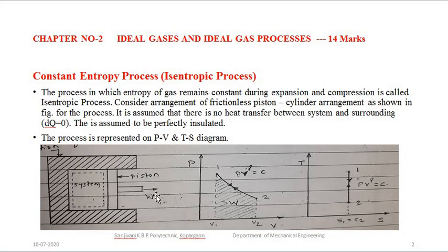Piston is moving towards the right hand side. We are getting the work output here. So we are having the work output at the expense of the change in internal energy, because we are neither providing heat nor rejecting heat. Therefore heat transfer is zero, but whatever internal energy is there of this particular system, that is utilized to produce the work in the isentropic expansion.